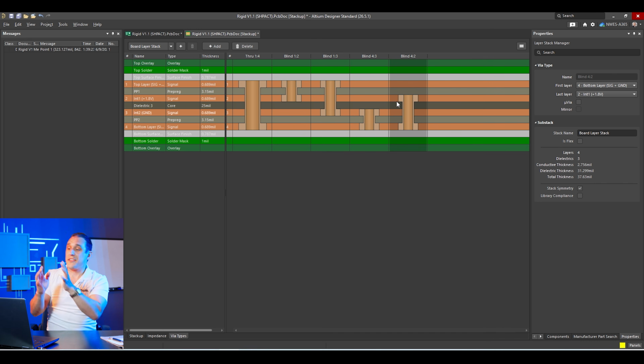So in conclusion, none of these blind vias as they're defined here are manufacturable, but I know why this was done. The intention here was to be able to define any blind via span that you want in this design without having to actually manually place blind vias from one layer to another. Unfortunately, in order to get the correct NC drill data out of this design and into your manufacturing files, you can't define these vias as groups.